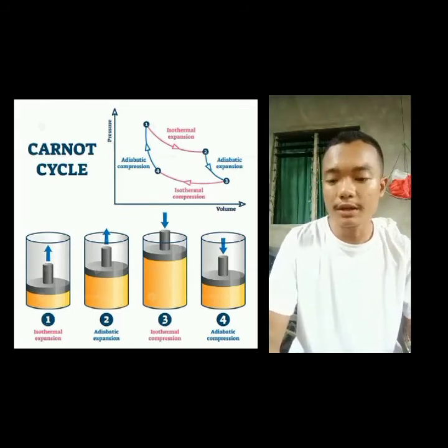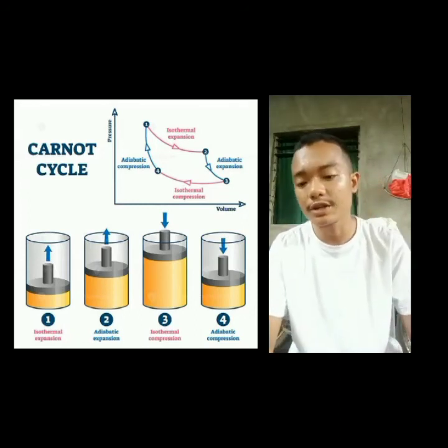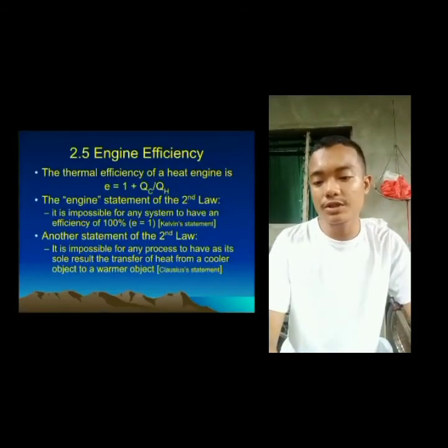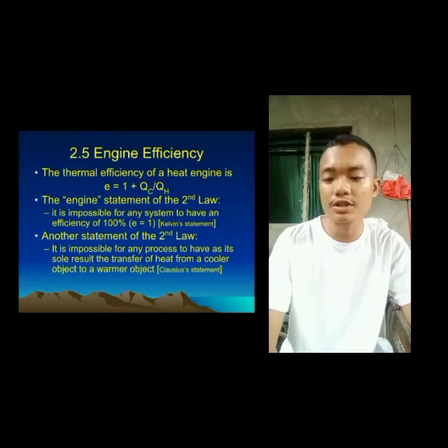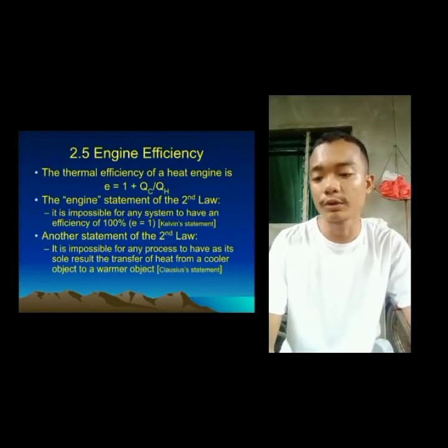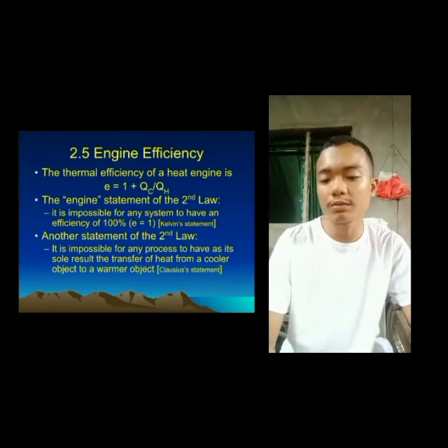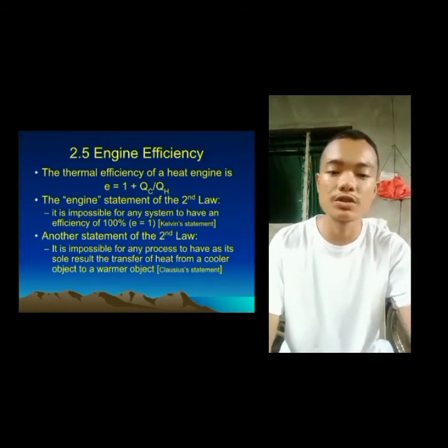Maximum adiabatic thermal efficiency is achieved by approaching the isothermal compression and expansion of the Carnot cycle, or by intercooling the compression and reheating the expansion process. Engine efficiency. Engine efficiency of thermal engines is the relationship between the total energy contained in the fuel and the amount of energy used to perform useful work. There are two classifications of thermal engines: internal combustion and external combustion engines.